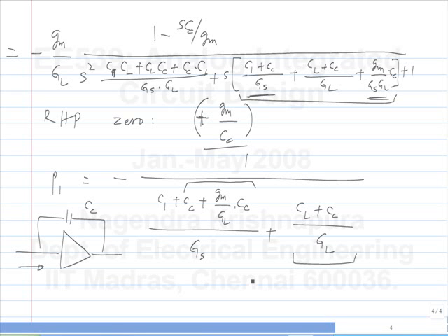So if you have a negative gain amplifier, it looks like Cc has become much larger, or the loading is larger than Cc. Now in our case, we don't have zero output impedance, so you have some extra terms. But largely, this is the capacitance that you have connected here, plus the Miller multiplied capacitance, divided by the conductance, you see. Okay? Is this okay?